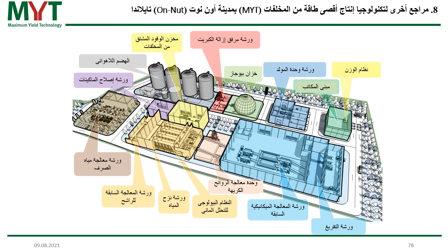You do not need additional water for the MYT process. We work with the water which is inside the waste. So every moment we get more water into our system with the fresh waste. In Egypt, you have more or less 50 to 60% organic waste. So you have sufficient water inside your waste to make this MYT process work.